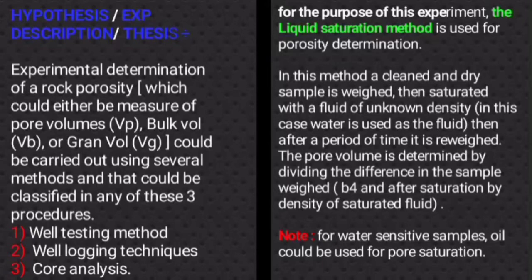After saturation for a period of time, like 1 hour, the sample is then weighed again. Now to get the pore volume, you have to find the difference between the soaked weight and the dried weight, or let me say the soaked weight minus the dried weight. Take note, for sensitive samples, oil could be used for pore saturation.